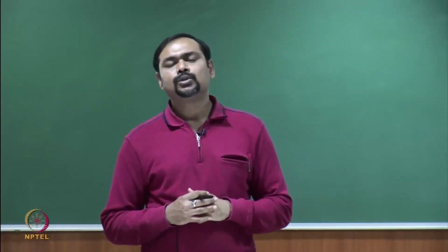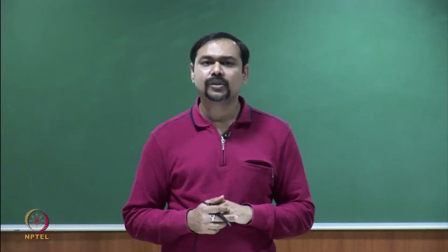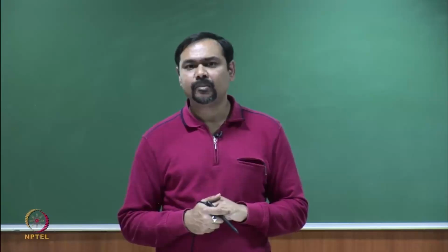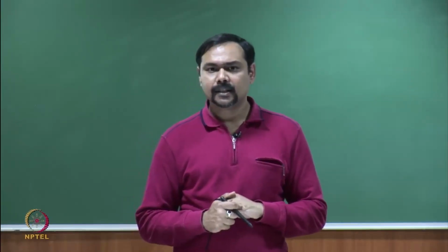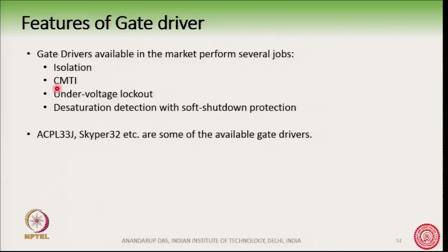So, the general trend is to use these commercially available gate driver ICs nowadays. There are 4 or 5 important terms. Apart from this, there are other important features also in the gate driver, but isolation, CMTI, under voltage lockout, DSAT detection, these are some of the features of gate drivers already available to you.